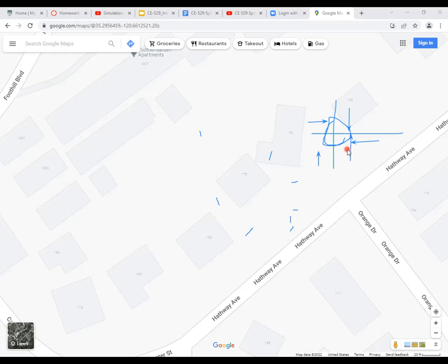So that's basically the assumption: if we make a good model that replicates the conditions and the type of behavior of today, we can now start to tinker around with things, like maybe convert a signalized intersection to a roundabout, or move 5% of the traffic from cars to buses or bicycles, and then see what time congestion might look like at different locations, things like that. You know, there might be some congestion we cannot do anything about, right?